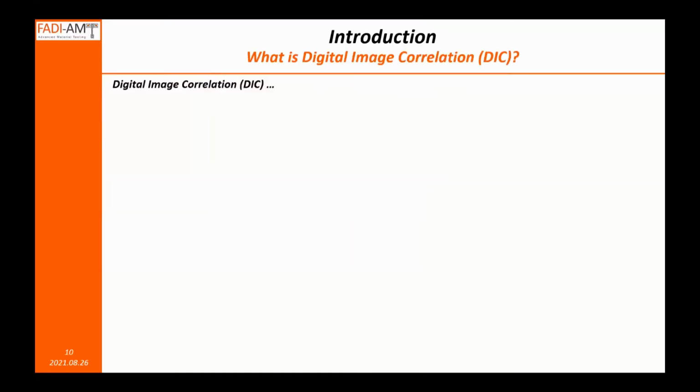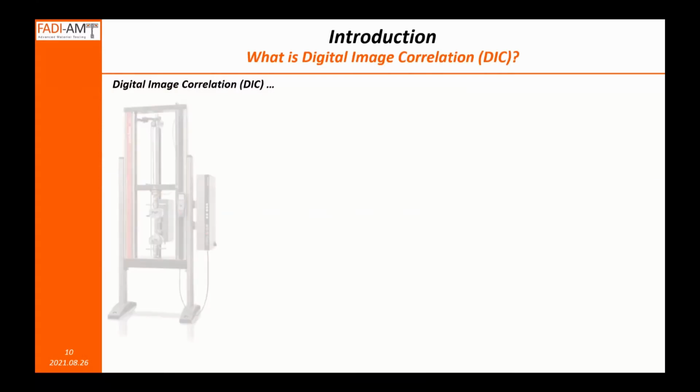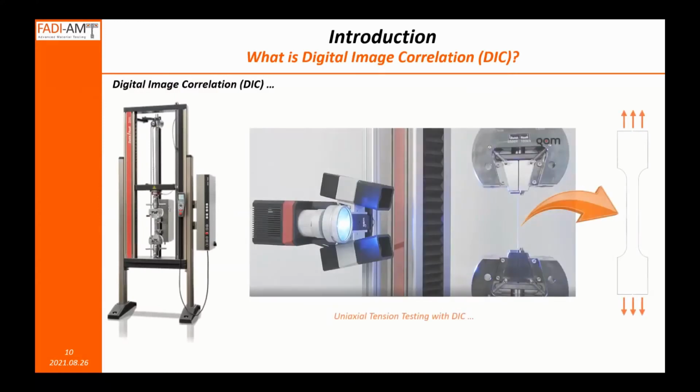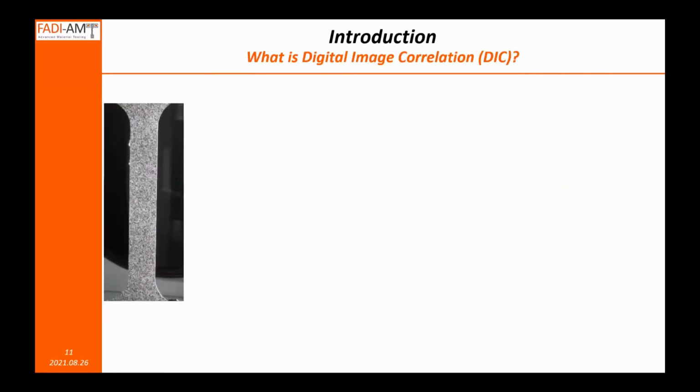So let's start with a very, very brief introduction about DIC, because I feel like after 2 or 3 years doing these webinars, most people are now familiar with the concept of DIC, and it's not really a new concept anymore. But just a quick reminder, we use this simple schematic to describe what DIC is based on a tension test. This is just a general image of a tension test equipped with a commercial standard 3D DIC system with 2 cameras, monitoring basically a tension sample during a standard tension test.